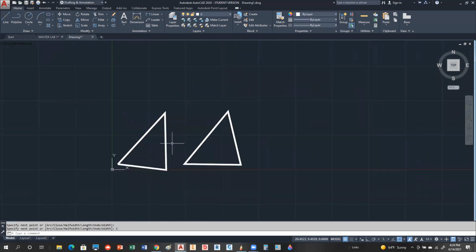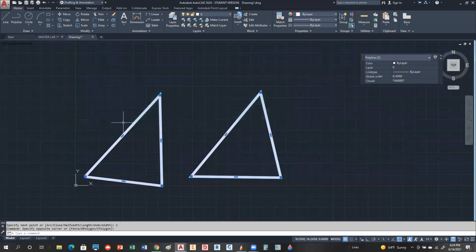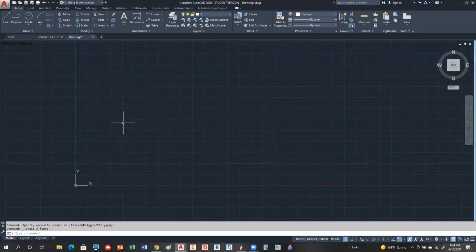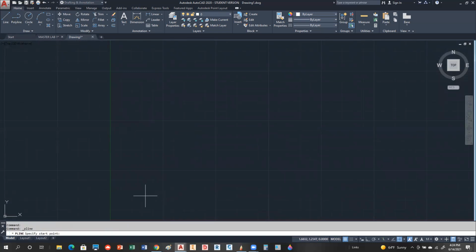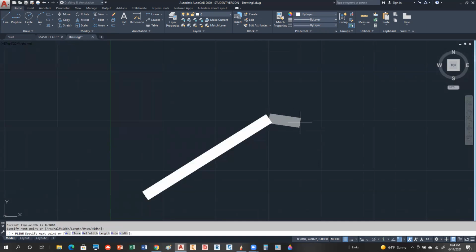All right, so I'm going to take these guys out. I'm just going to select them, and then hit delete. So the other thing you can do with a polyline is what's called a length option. You can just pick a point and pick a second point. I'm just going to leave my width on there because it's nice to see it. If I want to continue this in the same direction, but I don't know exactly what that direction is, I can use this option called length. That allows me to tell it how long I want it to be, and it'll know the direction that it's going.